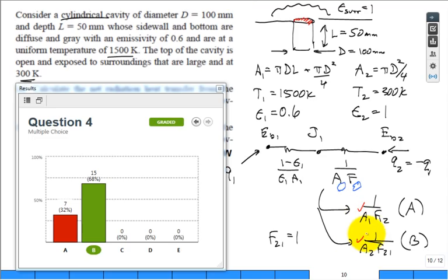So it's like there's 4 things to think about. A1, hey, no problem. A2, no problem. Haha, these view factors, they're always a challenge. But after you've done a few of them, oh, this one is unity. This one, 1 to 2, is not unity. And actually, the way I would calculate 1 to 2 is using reciprocity, which is essentially F1 to 2 is F2 to 1 times A2 over A1. So to calculate view factor 1 to 2, I would use the fact that I can calculate 2 to 1 first. So why not just use 2 to 1? So A2 F2 to 1. A little easier?